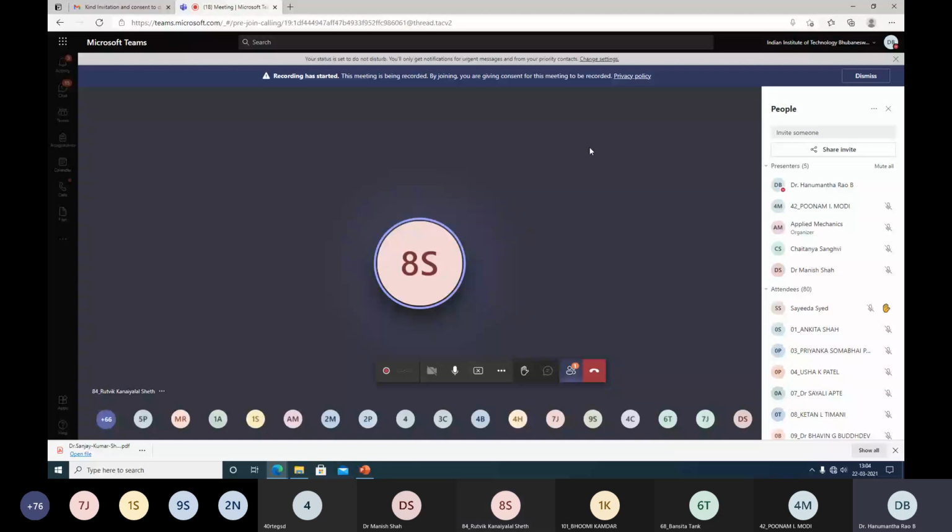Okay, so this is a twofold problem. One is assessing the red mud as a fill material, so for that purpose you have to go for the mechanical compaction characteristics. And at the same time, if you want to use the red mud as a bottom liner, then you have to go for other characterization, which is more of an environmental concern. Yes, the first one is a geotechnical concern. The second one is an environmental concern. Right, sir. Thank you.